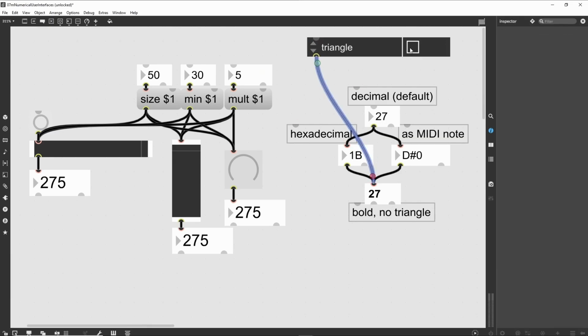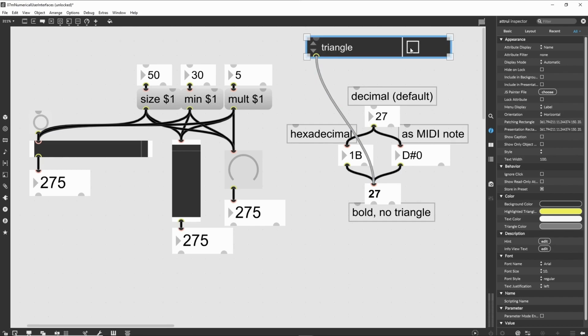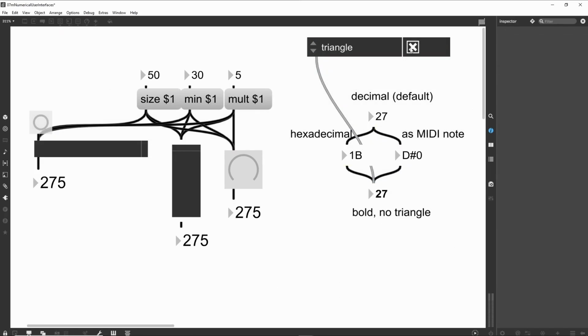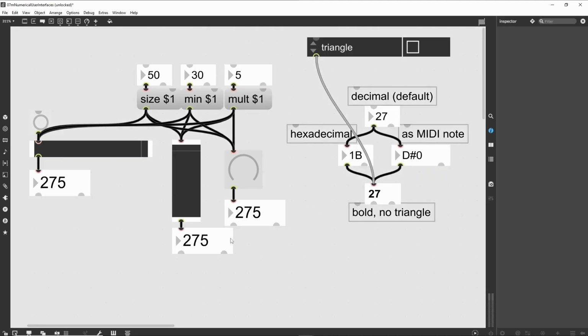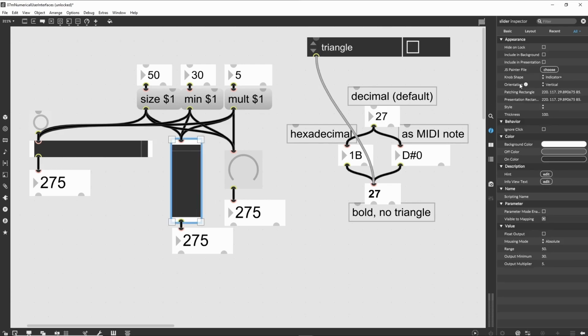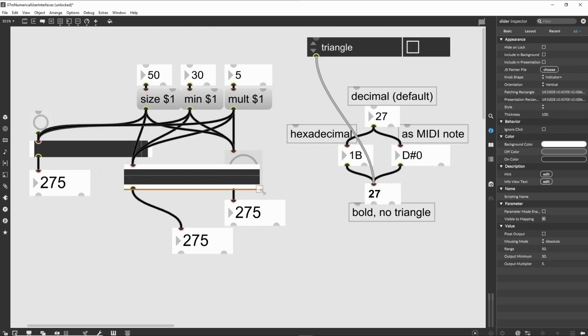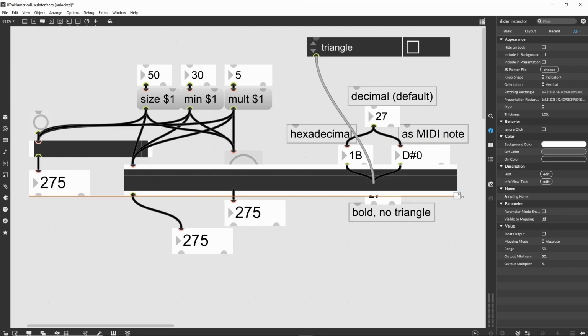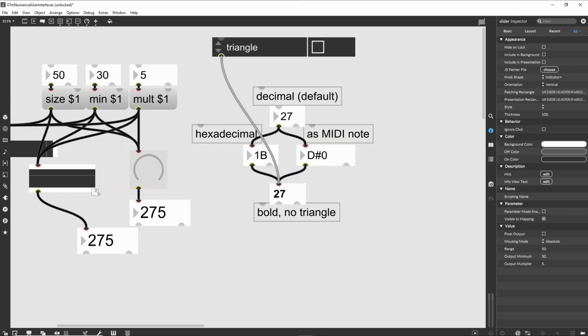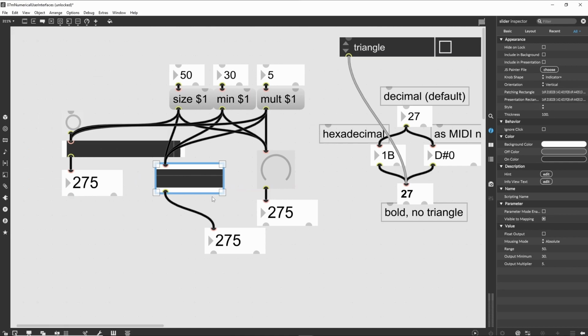Using the inspector, let's unlock the patcher and create our own small user interface. Select a slider, a dial, and a number box from the top patcher window toolbar palettes. Resize them to be different sizes, and move them around to make an attractive layout. Note how the slider switches from a vertical to horizontal orientation depending on the aspect ratio. Connect the objects to see how they interact, and use the objects as both display and editing tools.